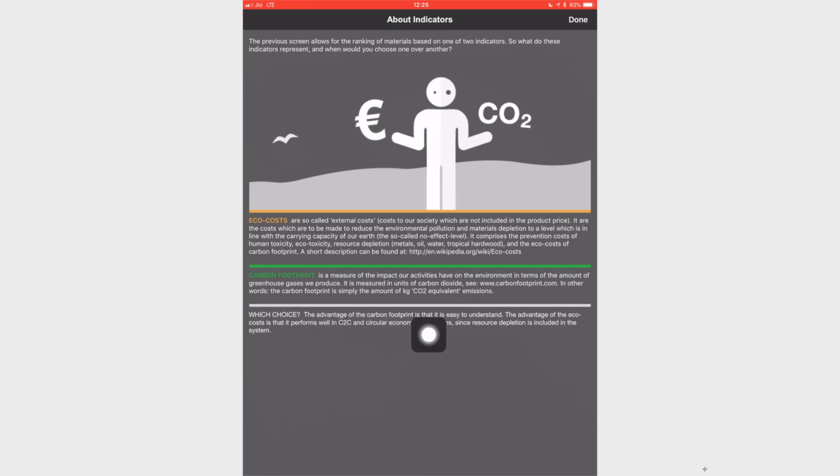My first material to add is PET. So, I go to plastics and try to find PET. Here you can see this is PET bio-based, which is the PET meant for making bottles. So, it is not a biodegradable or bio-based plastic. What it means is it is a bottle grade plastic. So, I will select this option, LCA. I click on LCA, and it is added to the project.